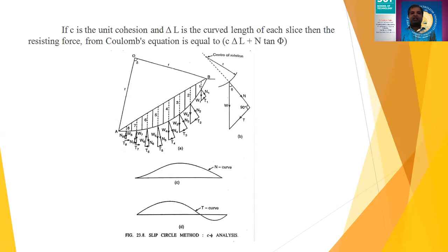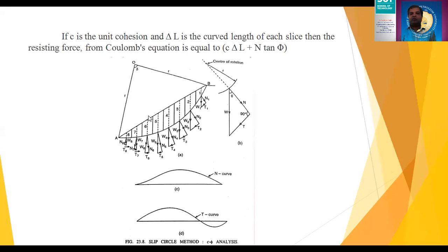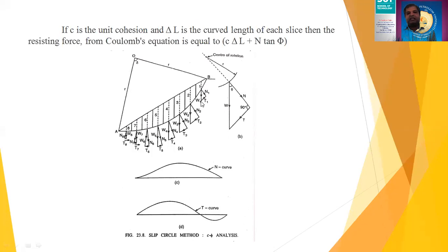Once you do this, you need to find out the center location by means of a dotted line. So I have plotted this center location by means of the dotted line. Now, for each component of the slope, first you measure this particular length. You can see this dotted length, you first measure, and the same length you pass on here. So this will be the weight component. Exactly this length and this length will be similar. Similarly, this length and this length will be similar. So just pass on this length to the end of the slice as a component of weight.